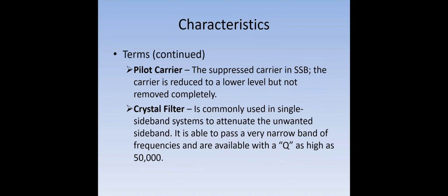Okay, pilot carrier, the suppressed carrier in the single sideband, the carrier is reduced to a lower level but not removed completely. The crystal filter, commonly used in single sideband systems to attenuate the unwanted sideband, is able to pass a very narrow band of frequencies and is available with a Q as high as 50,000. And remember, the higher the Q, the better the selectivity, and also that crystal oscillators are the most efficient oscillator